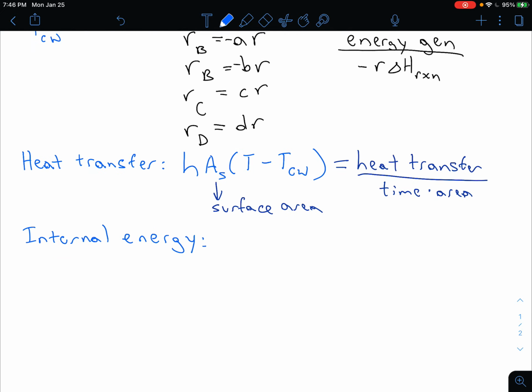So we're going to use the following simple equation: the energy per unit fluid volume is going to be the density of the fluid, rho, times the heat capacity of the fluid, Cp, which both of those we're going to assume are constant, times the temperature of the fluid minus Tref.